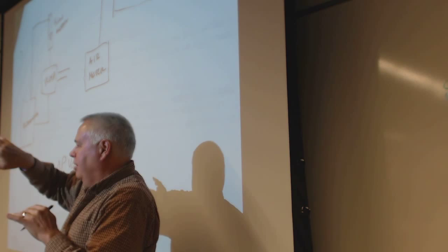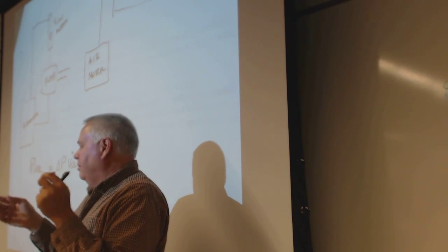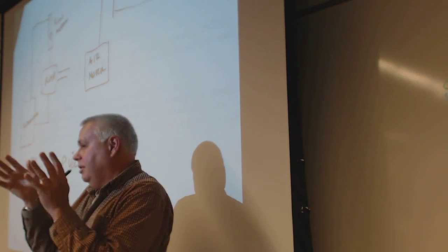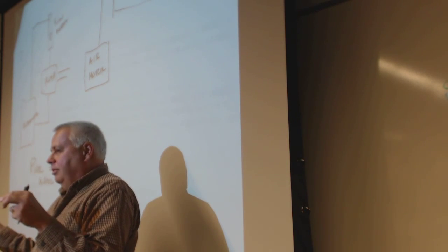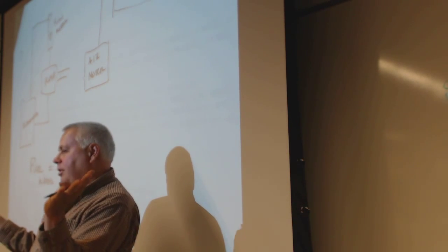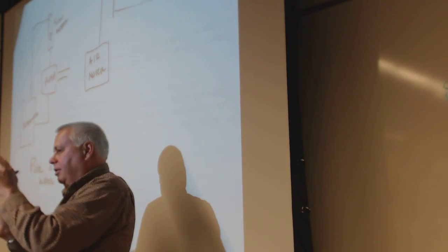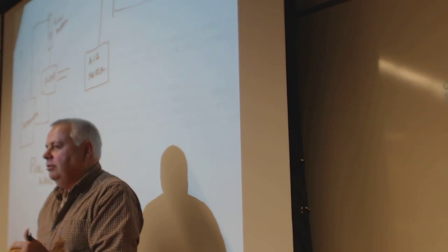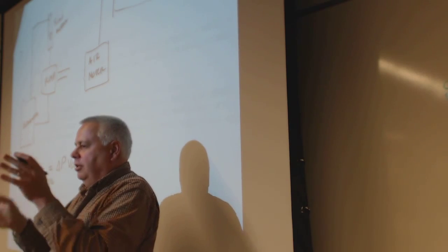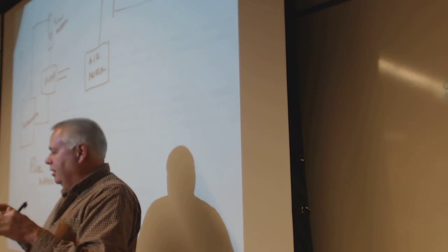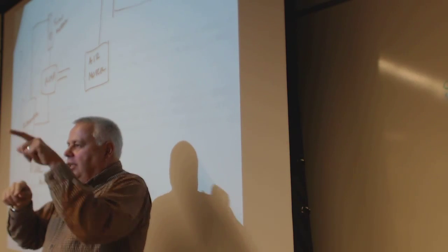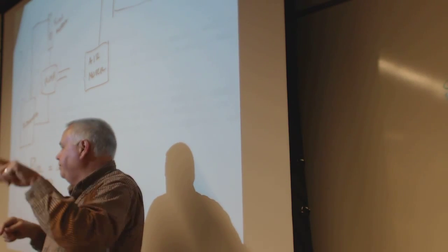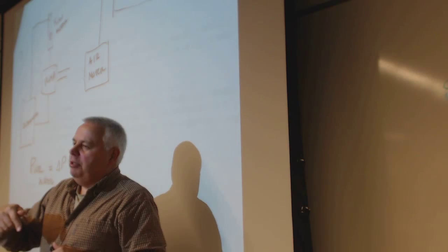And the pressure pushes on one side of the plate, pushes on both sides actually, but one side will be seeing exhaust, exhausted to the atmosphere, and the other side sees the high pressure, and it's trying to push on the plate, and that's what rotates the motor. And the plate gets larger and smaller, high pressure, low pressure. There's not just one plate, it's like 8 or 6 or something, as it goes around. And we're applying compressed air to it.